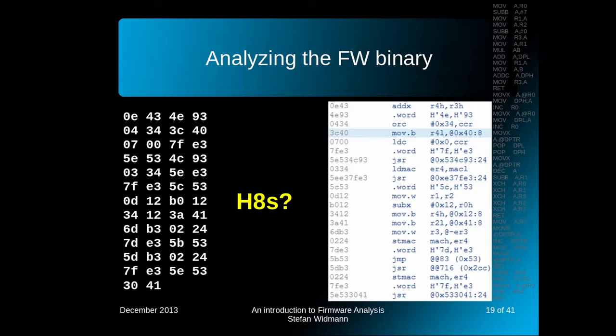Take some time and please raise your hand if you think that this is valid disassembly and we have found our architecture. Okay, I see one hand. Okay, I have to disappoint you, I'm sorry. It's not valid disassembly. We can see it in the second line. The disassembler was not able to disassemble the data, and it's just an undefined instruction. There are several .word entries in the code. So it's not H8S.